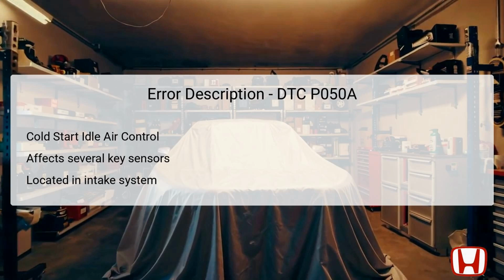DTC P050A refers to a performance problem within the cold start idle air control system, often connected with various sensors and components like the throttle body and air cleaner. The cold start system is designed to ensure the engine receives an appropriate air-fuel mixture during cold starts, optimizing performance when the engine is not fully warmed up.